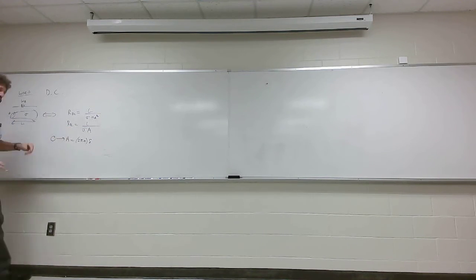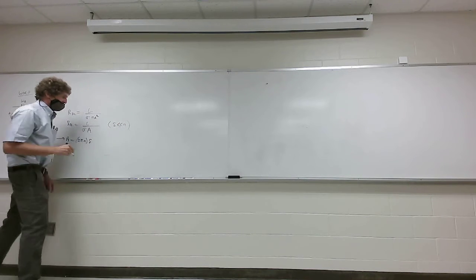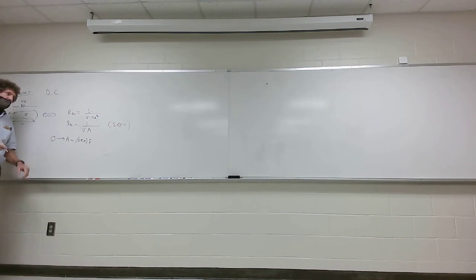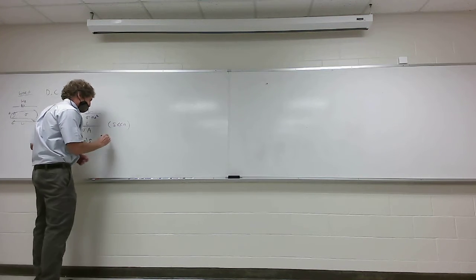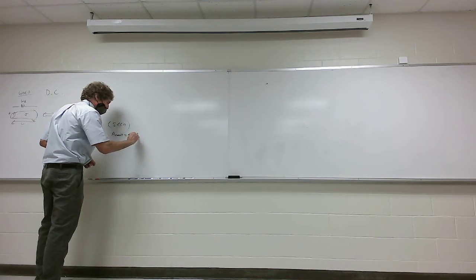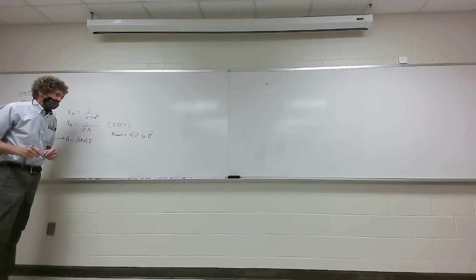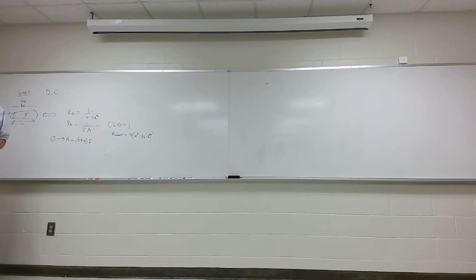So this is AC, and I hate to have to qualify this, but this is when the skin depth is much less than A. In between, you can write the exact formula for A. A exact is just going to be pi times A squared minus A minus the skin depth squared. But here, the skin depth still has to be less than A. Do y'all follow me on that, class? This one will work, but you're almost never going to have to do that. Yes?